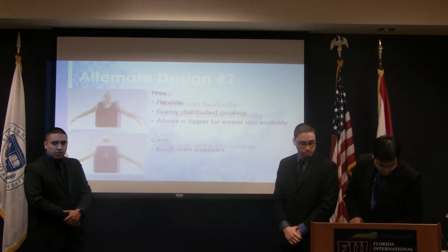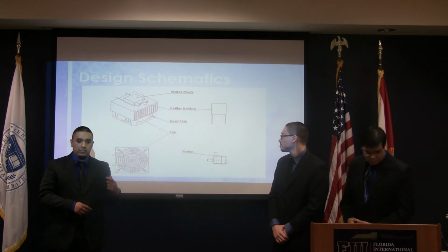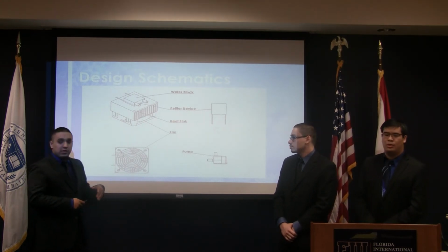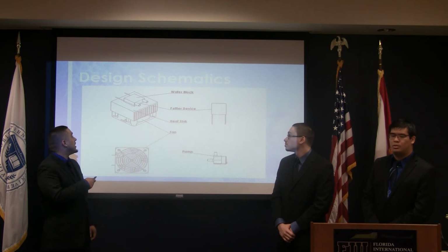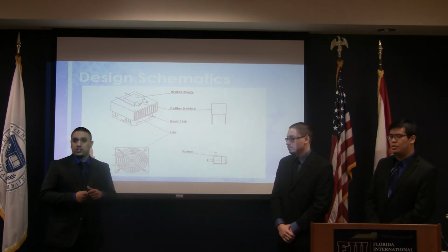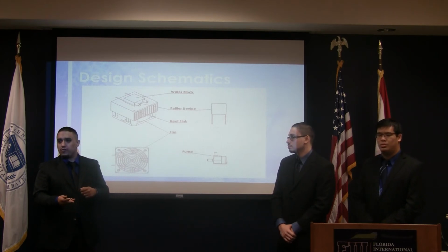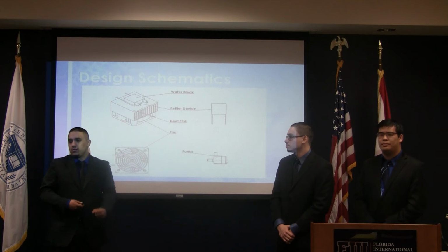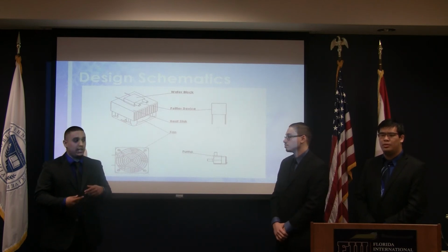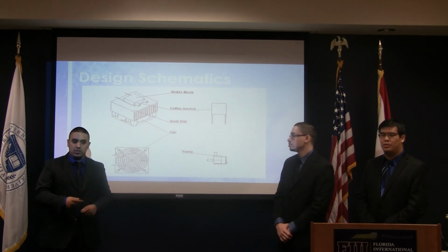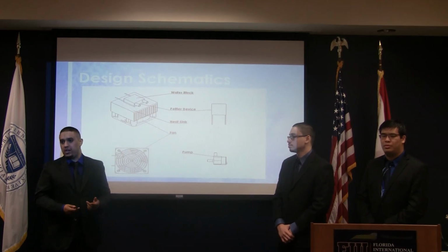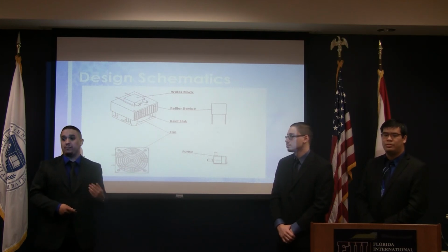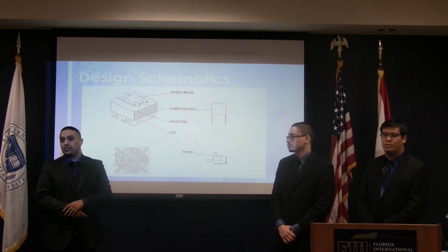The way this was designed was specifically for easy maintenance. The idea of the submersible pump, this pump right here, is that it will be one closed loop between it and the water block that you see at the top. So when you want to refill or take out water from your system, it's as easy as putting that pump into a sink or somewhere with a large container where you can submerge it. The whole purpose is to make it easy for the user to fill and dispose of their water as they see fit. Let's say they didn't use a biocide through their tubing and it gets algae or something. We wanted to make it easy for them to replace the water that travels along in that tubing.